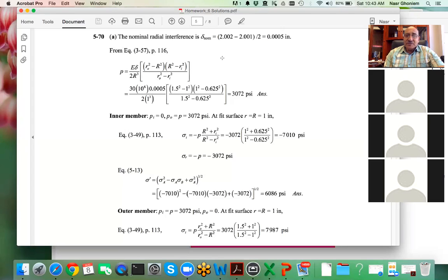I think most of you did okay, but there was a challenge in it, definitely, because you had a force at the junction between a thin section of the shaft and the thick section, and that caused the moment over I diagram to be challenging.